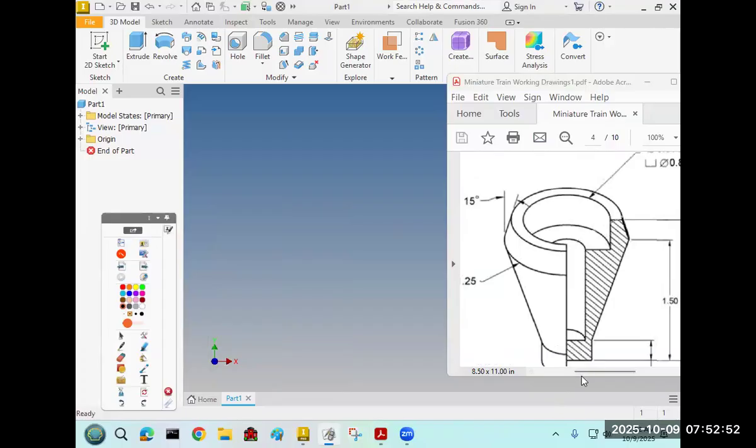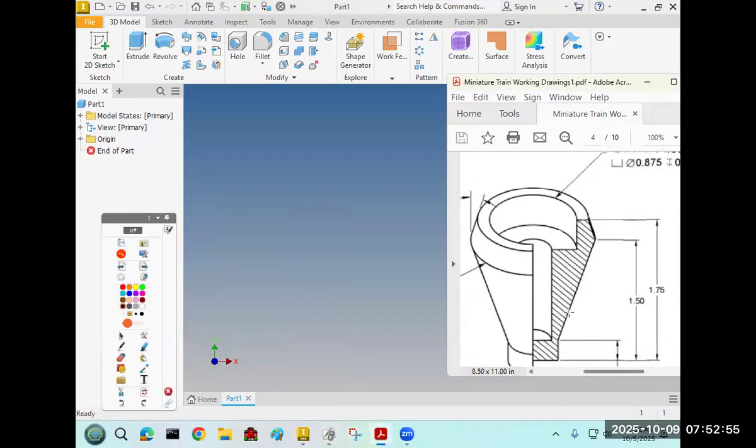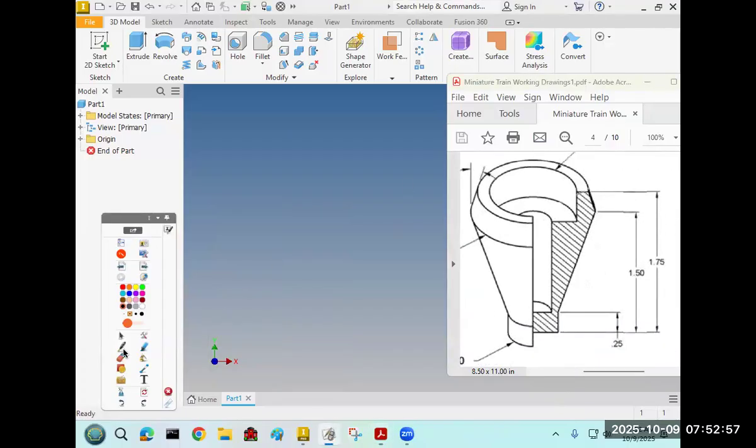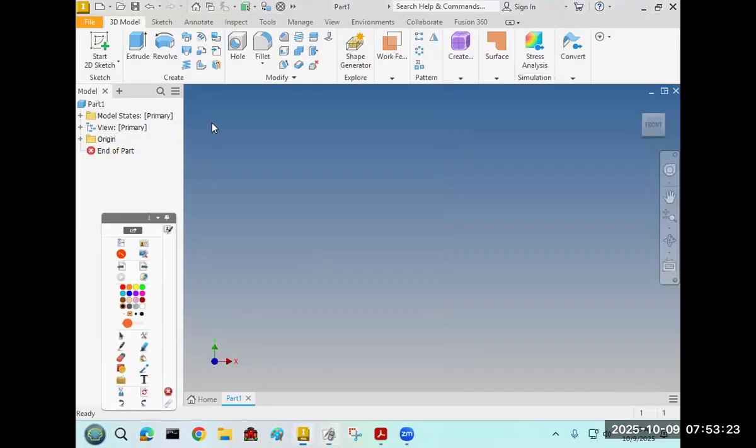As we have in the past, when we're doing any sort of revolve, like we did with the pegs, the key is deciding what your center axis is going to be. And clearly, this is our center axis. That's going to be our first line. And it's going to be, in this case, the total height, which is 1.75. Then I actually need this to be smaller.